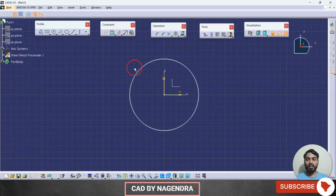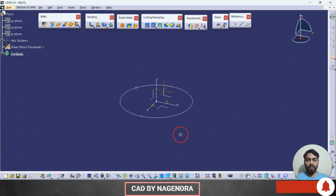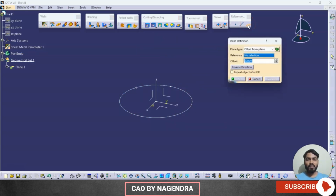For example, on the top plane, we have one circle here. Along with that, we need to create one point. Why this point, I'll tell you later. Then, from here with some height, I need one more circle. We can't create it directly at some height, so we need a proper reference plane. I'll click on reference plane, offset from this top line at some height.